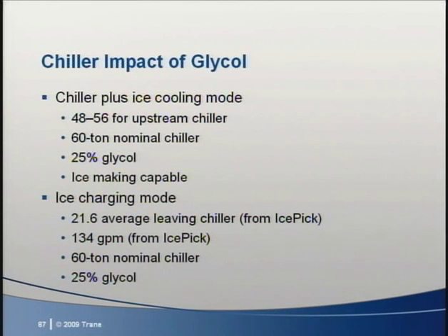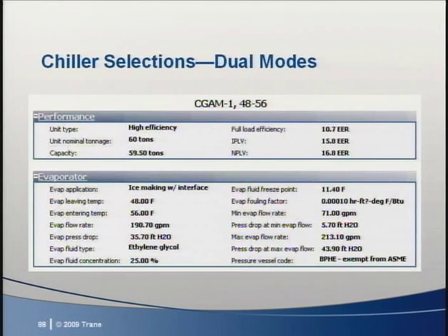These were determined by the nominal chiller size, the hours and spare capacity available for charging, and the number of tanks. Here is our 60-ton chiller during discharge plus cool mode. We've got a 10.7 EER, and we're making 48-degree water, which is halfway from 40 to 56. For modeling purposes, we don't need the part load value because this is handled with the unloading curves in Trace.